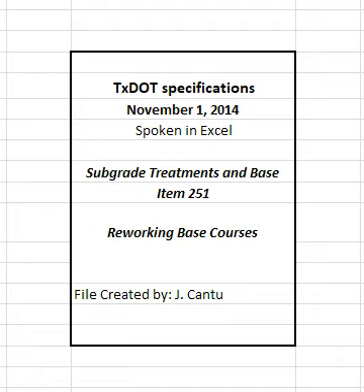Shape and maintain the course and surface in conformity with the typical sections, lines, and grades shown on the plans or as directed. In areas where surfacing is to be placed, correct grade deviations in excess of 1/4 inches in 16 feet measured longitudinally for the entire width of the cross section. Correct by loosening, adding, or removing material. Reshape and recompact in accordance with Section 251.4.3, Compaction.